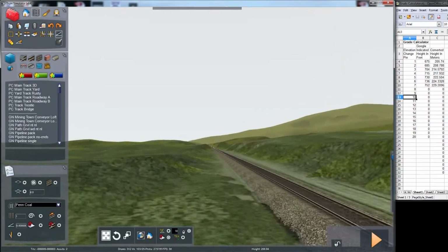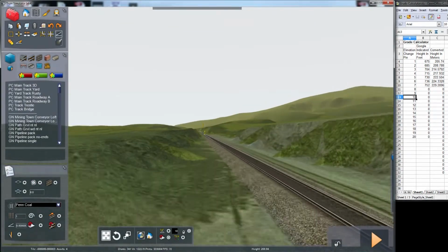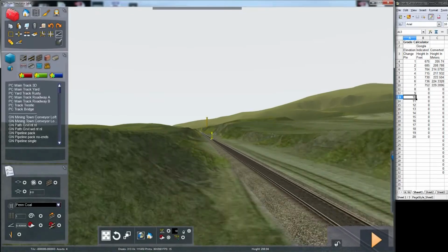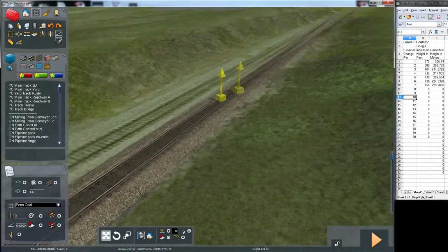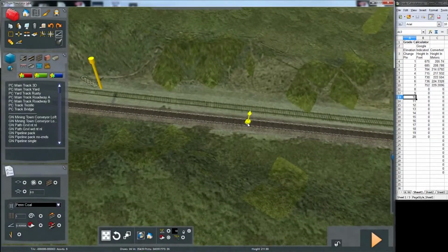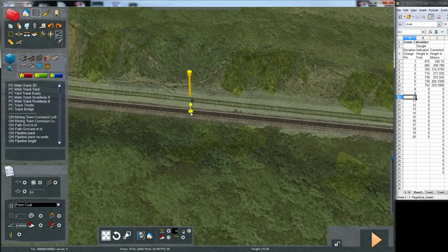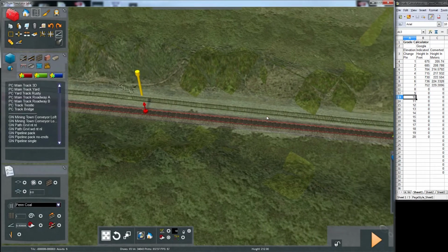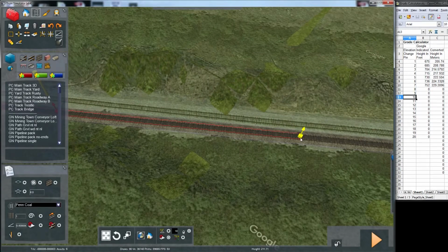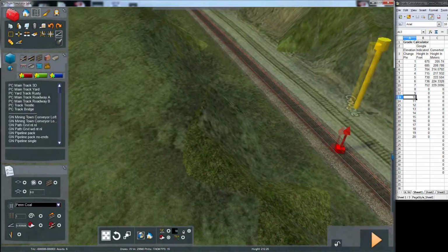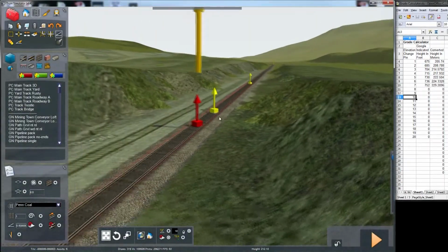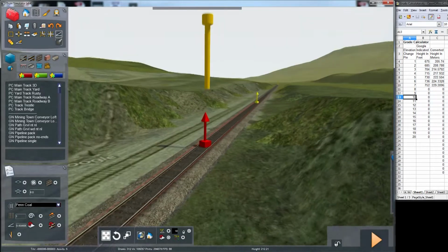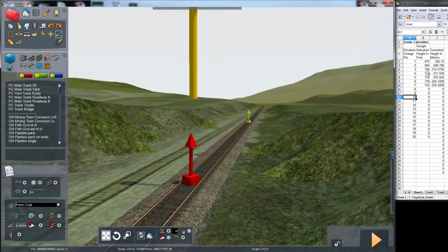Go to the next pin. Now this may be a bit of a problem because we actually had that elevation pin set a little over 500 meters. And you see we don't have an elevation arrow here, so I'm going to put one there. But now I've got this one in the middle of things. We'll have to raise it up to something that corresponds with the elevation it should be by sighting the track, and I'll show you how to do that. So this marker should be 704 feet, or 214.57.